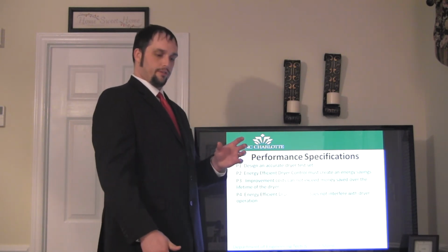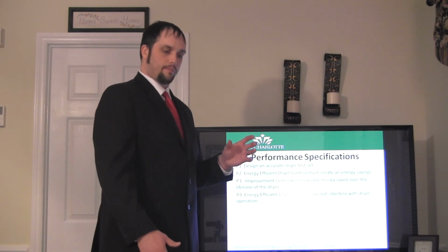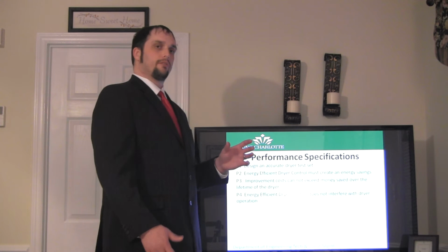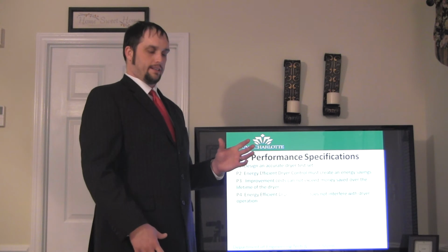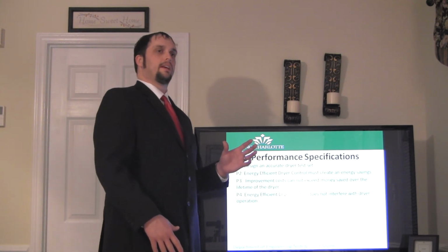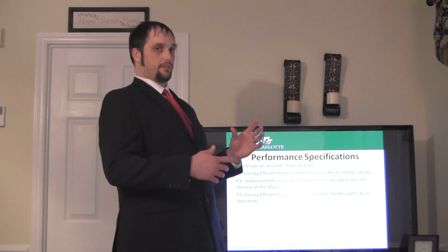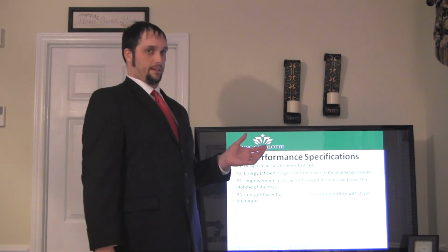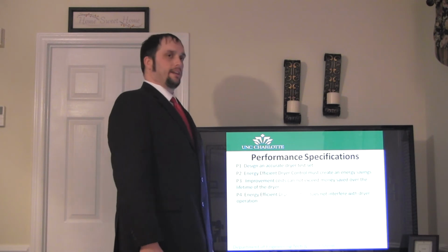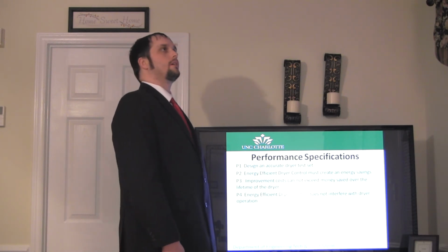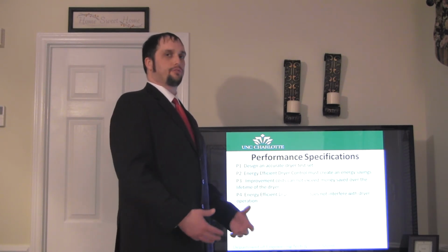So your dryer attachment that's on your exhaust will monitor the relative humidity, temperature, airflow, and when it reaches a level that says that the clothes are dry, it'll turn off the relay that's allowing power to go to your dryer. So basically, the attachment should work on any dryer and not affect the operation, because it's not an intrusive attachment.